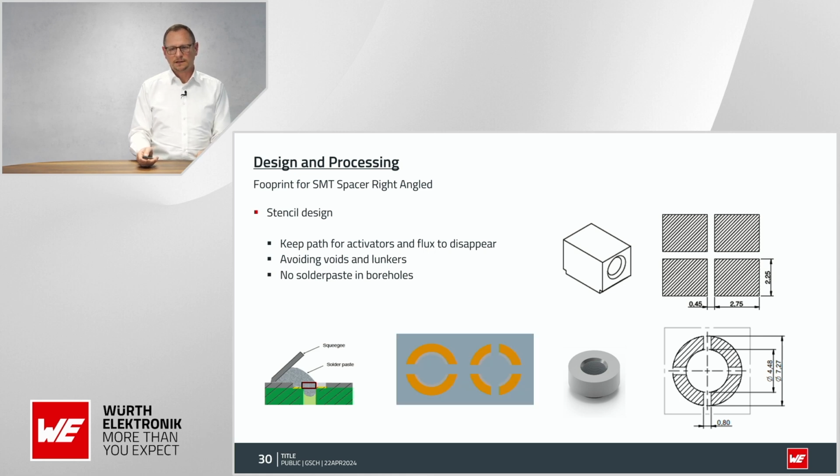This could look like this, for example, from the shape. What is also possible in your calculation, if you can't achieve enough volume for the solder paste, you can also overprint a little bit directly on the solder resist. This will do no harm to your solder resist. During the soldering process, all the solder will be drawn directly onto the copper fields.